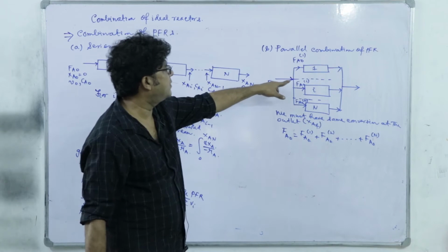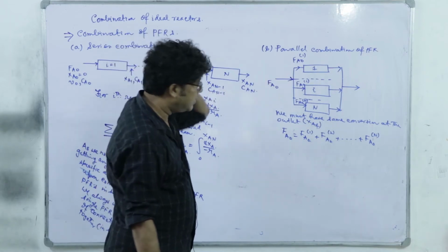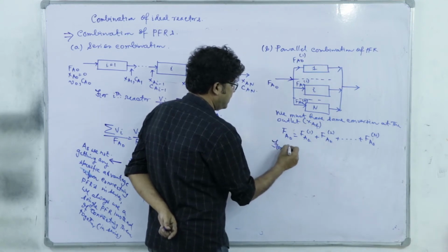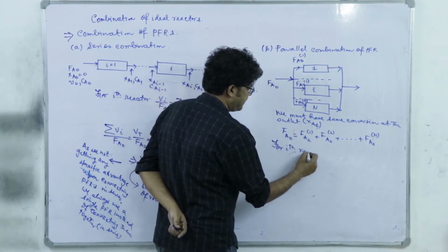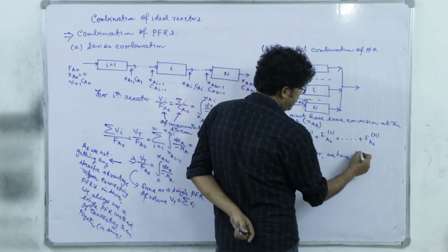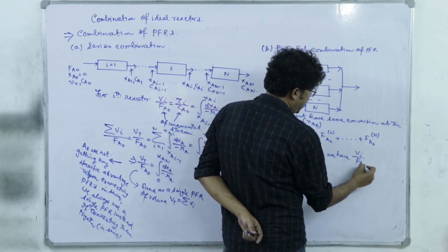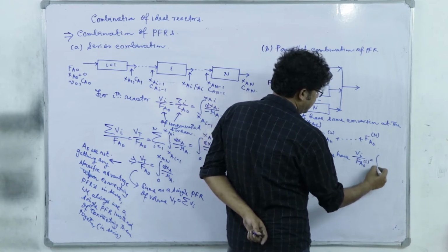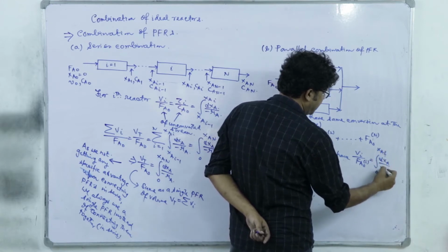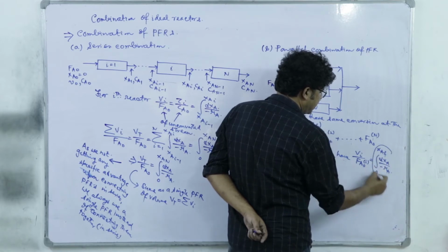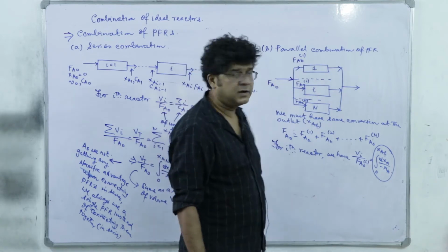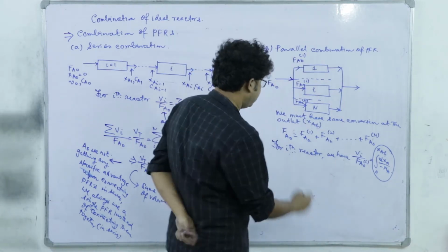Right, that is obvious from this balance at the point. And if I want to have the same conversion for ith reactor, we have Vi by Fa naught i equal to 0 to XAF dXA by minus Ra. So, we need to note that this part should remain constant for all the different parallel branches.